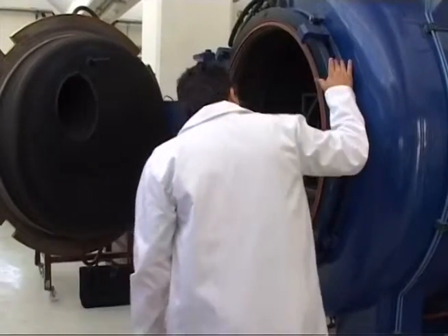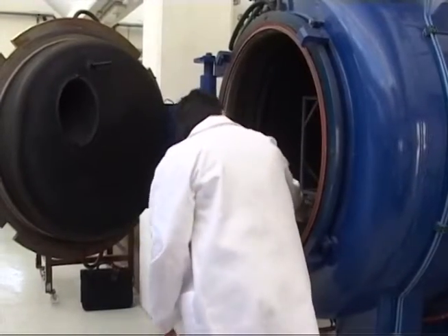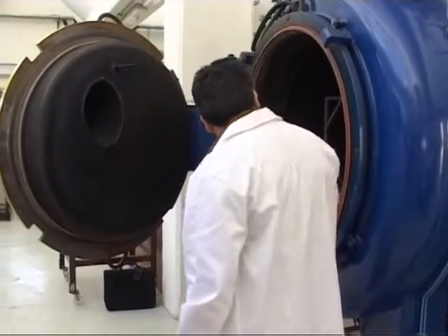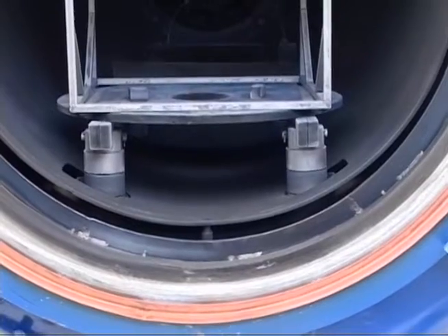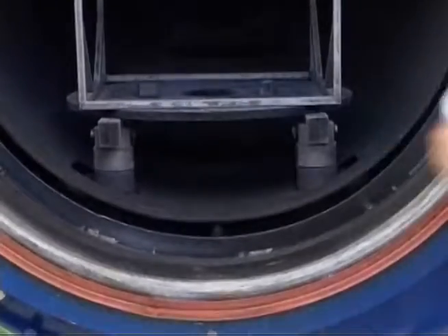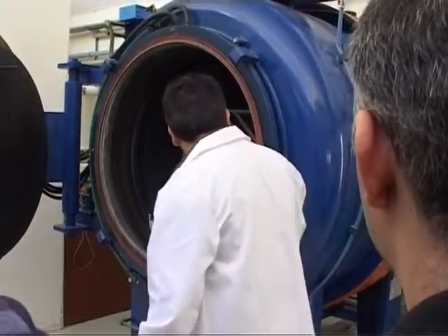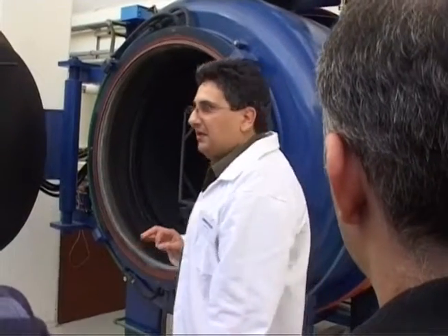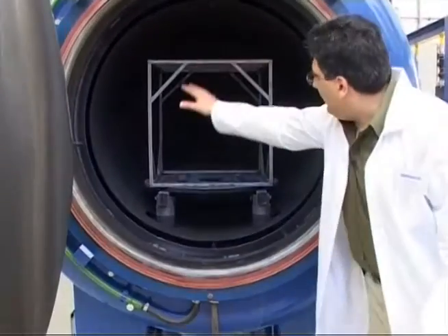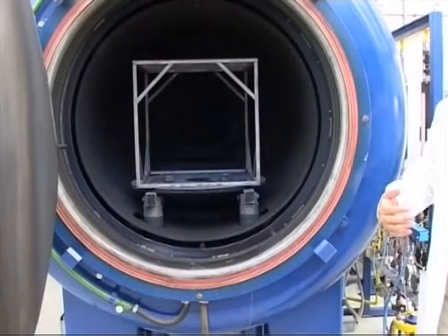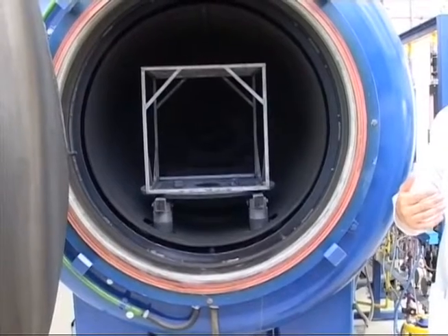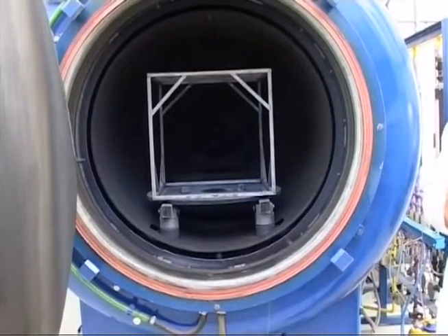So, if we have a look inside the furnace, we see that there is the table which supports the workload, and the table is mounted on 4 isolating mounts. Inside these metal cups, there is a ceramic cap which electrically isolates the table from the wall of the furnace. This is necessary for plasma nitriding, where the work inside the furnace is set to a higher potential in order to accelerate ions towards the components.